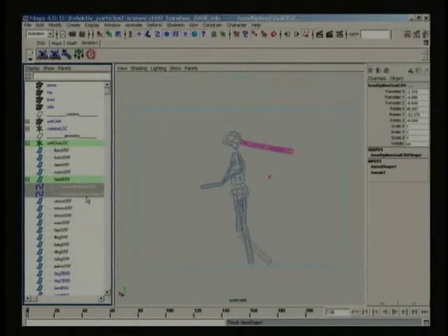This allows me to apply deformations to the goal curve so that when my goal lock is set to 1, the softbody will conform to the deforming curve, as all the particles' goal PP will be set to 1. When goal lock is 0, the particles will follow the original curve using a combination of dynamics and goal PP. I now have balanced control between dynamics and keyframed animation.